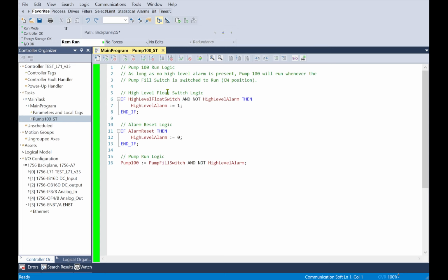This is what you come up with, the same program when I just did the AI conversion. It took 15 seconds to do the whole process. But I'm going to turn input 4 on and off. Well, you don't see anything happening really. You can if you right click and go to the monitor tab and then come back, but you don't see it all happening together. And then the float switch, it's open, it's closed, it's open, and you see nothing. So while this program might work functionally, it doesn't have the tools for troubleshooting.